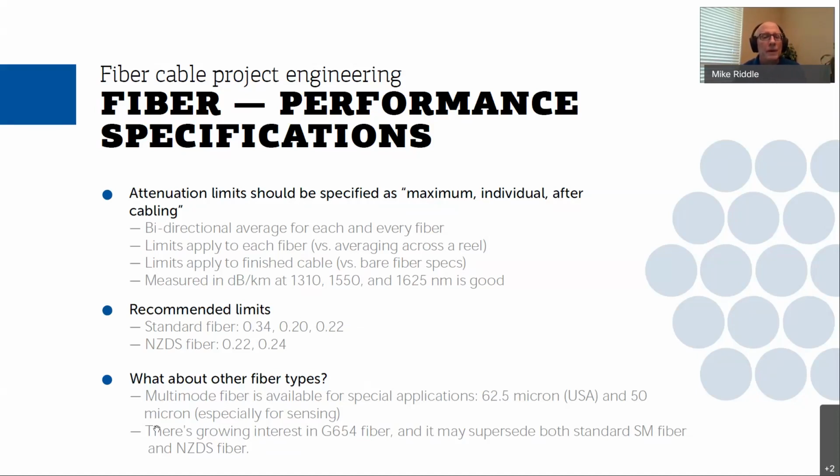There are other types of fiber out there. Not going to talk about it in detail today. There's G654 fiber, which is kind of a new generation of fiber that's trying to combine the points of standard low water peak single mode fiber with some good features of non-zero dispersion shifted fiber. Talk about it on another day. There's also multi-mode fiber that comes at utilities from time to time, and if it does, please just let us know. We'll be glad to help you out. For today, I just want to focus on the standard low water peak single mode fiber.